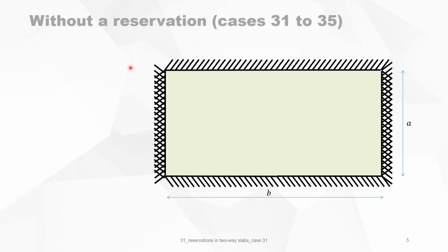Let's start with the horizontal case where the yield line is horizontal. The yield line in the corner where two rotation axes cross, we use the 60-30 degree rule. So this is 60 degree on the side of the fixation and 30 degrees where it's simply supported.